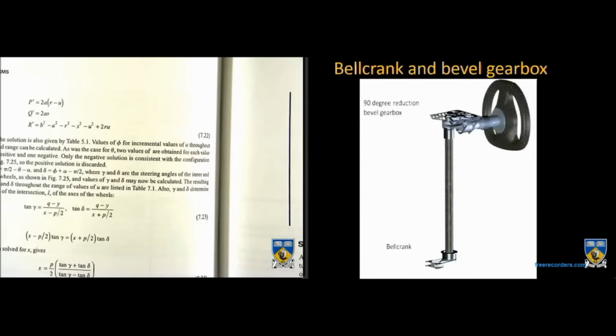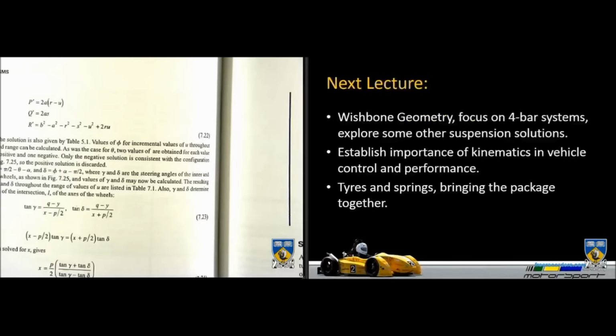There's no uni joints to worry about compliance. And by swapping out that one bell crank, you can actually change so many of your system parameters. And then again, it's through your tie rods, through to your wheels again. So that really wraps that one up.